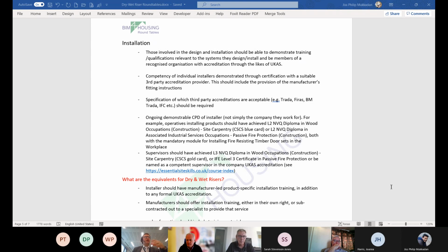But you're right. We've had projects, which you've corrected, where I've gone down simple things and found busbar without compartmentation seals on it, because the guy that's buying the busbar is 4 tiers down the chain. They've never seen a fire strategy drawing. They don't even know what they're looking at.